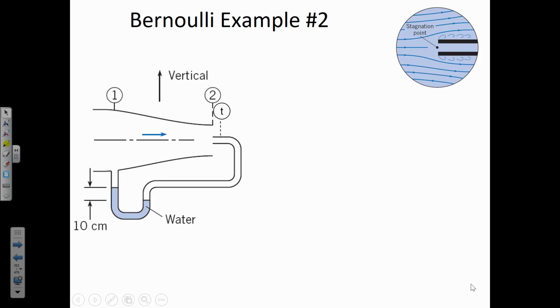The way that they work is that they measure pressure differences by having static conditions inside the manometer. So the wind is going through this nozzle, but the wind isn't going into the manometer. This manometer opening is measuring the difference in pressure between this opening at the wide section and this opening at the narrow section.